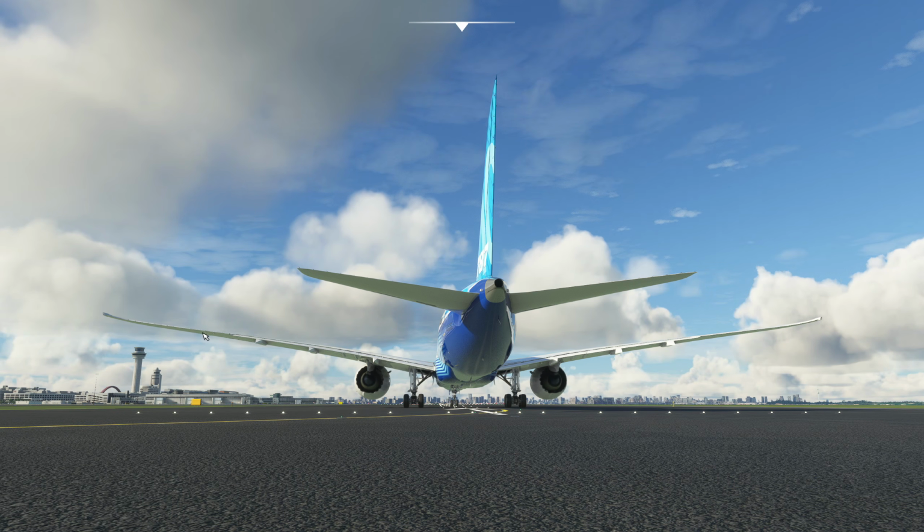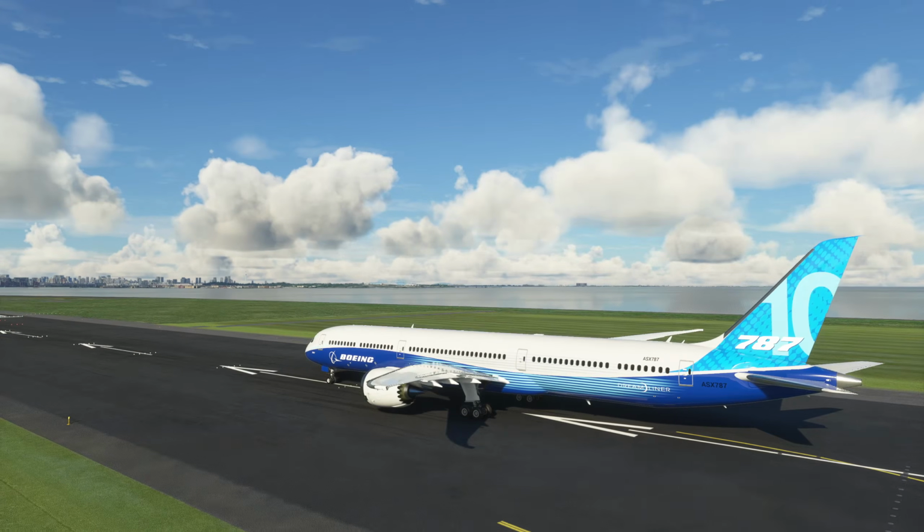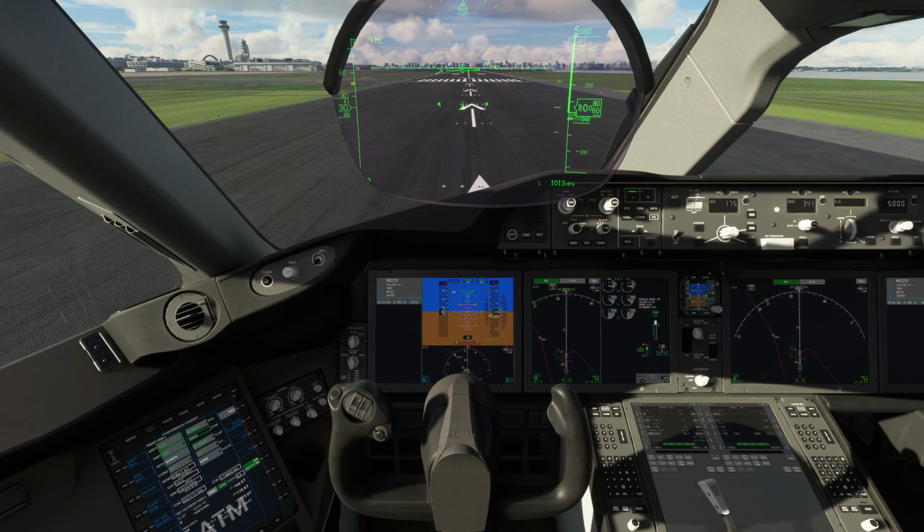You'll see it if you're ever a passenger on a 787. You'll see them bending way up. As they get higher, the wind can get underneath them more, so you'll need that into-wind aileron to keep the airplane level. We want it level during the takeoff roll. We're looking to keep perfectly wings level.